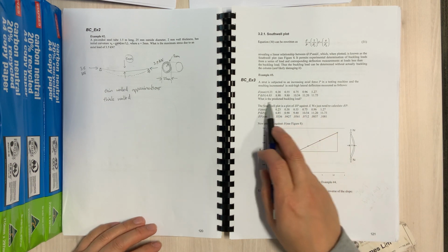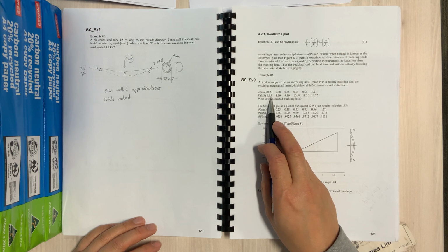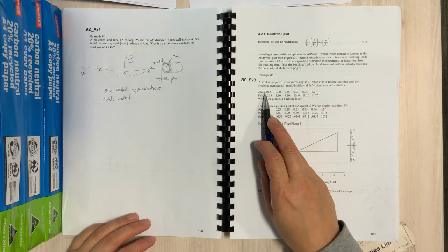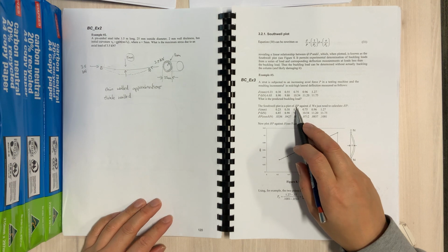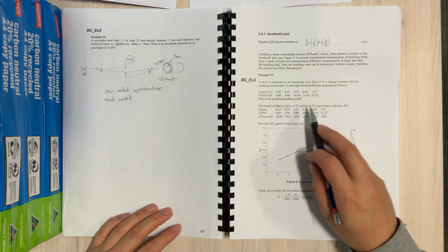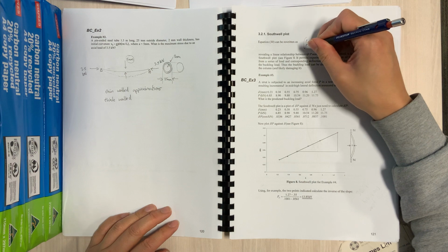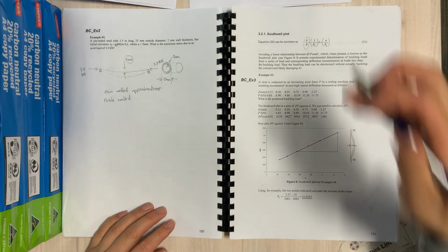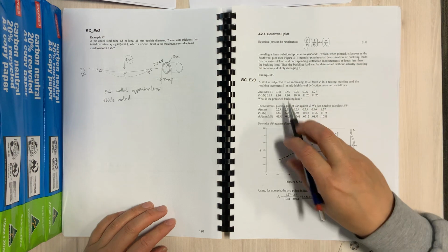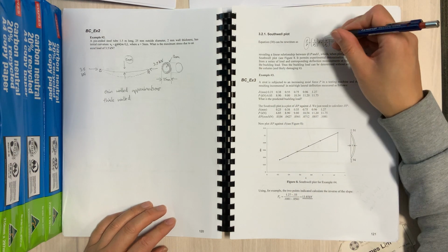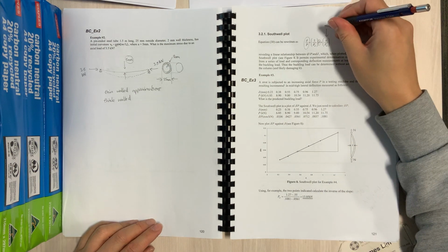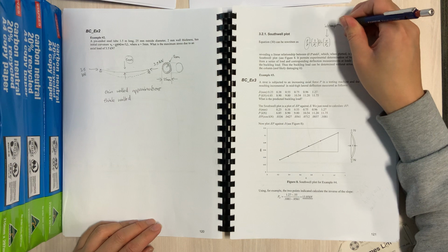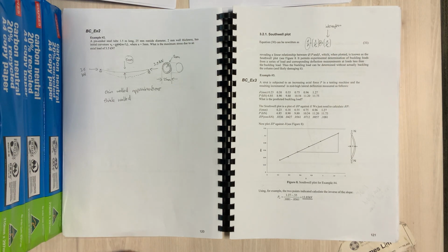So this has all been tabulated with the different values of P which you've stuck onto it, as well as the additional deflection delta. What is the predicted buckling load from all of this? So you would do the Southwell plot. You've got delta over P against delta, so we're plotting Y on that axis, and then on this axis here we're plotting delta, so that becomes Y equals mx plus c, so that obviously becomes the intercept, which you're not so worried about, and then 1 over delta c would become the gradient.